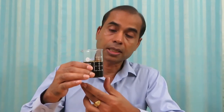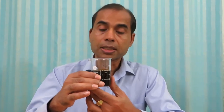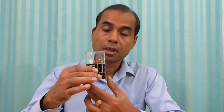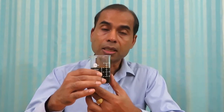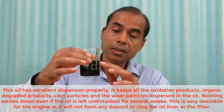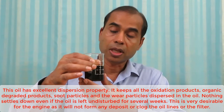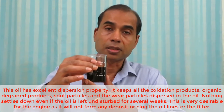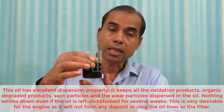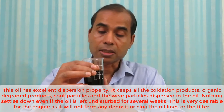But one thing we can see is that this oil keeps all the wear particles and oxidation products in dispersion. So even if I keep it for a week without touching it, nothing settles down. Everything is in suspension. So that means the detergent and the dispersant is working very well. So this kind of additive will not make any deposit on the metal surface.